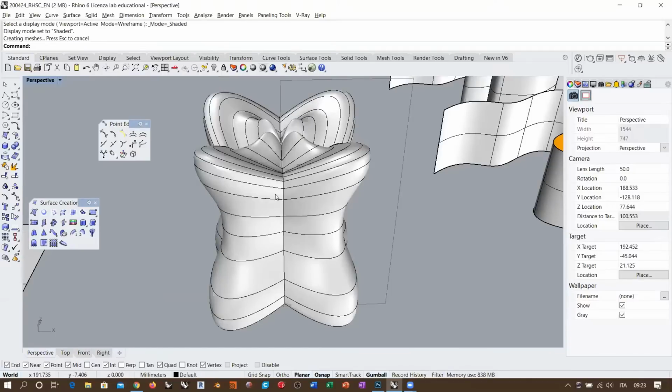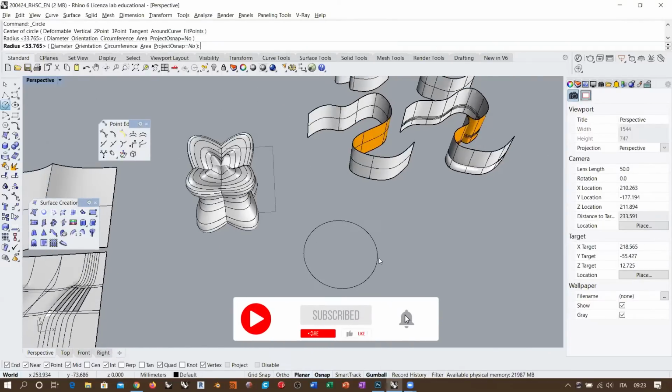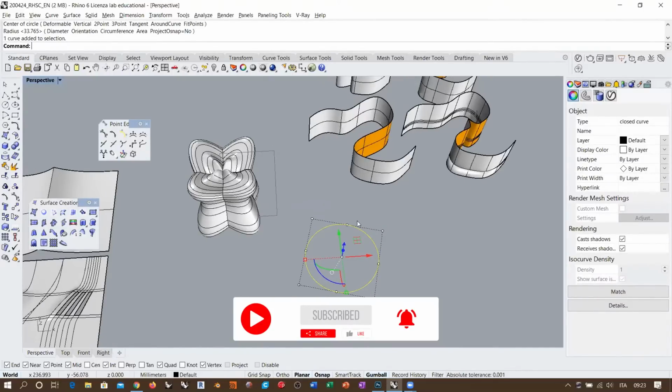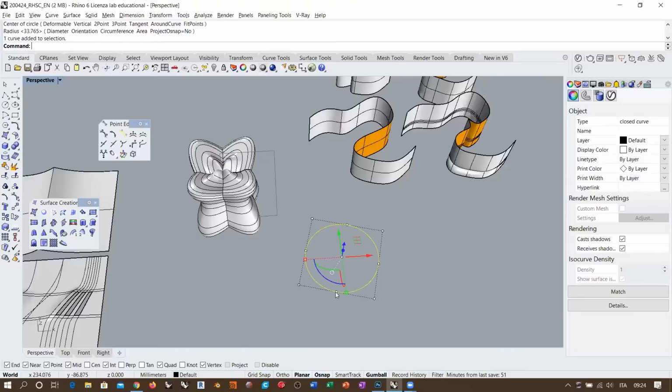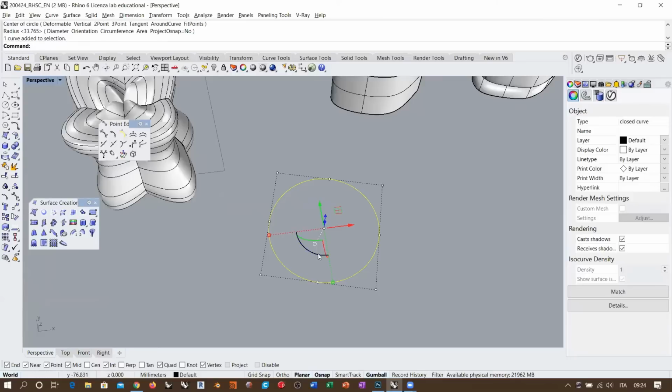So you see that, and this is also valid for the standard circle. You see that here we have these control points that lie on the surface, and we saw that when we have control points that lie on the surface, these are most likely kinks or knots with full multiplicity. In this case, if we analyze the knot vector of a circle, these knot values would appear twice inside the knot vector because this curve has degree 2. Okay, so full multiplicity for a degree 2 curve means that the knot value appears twice.